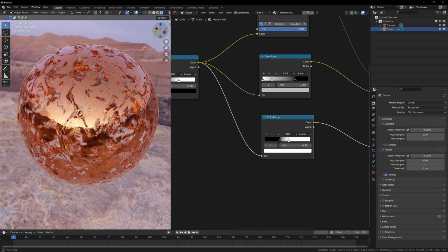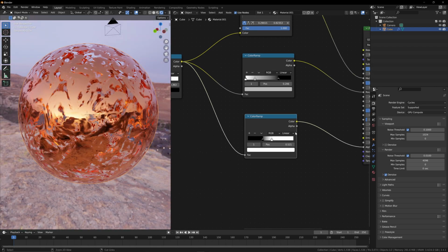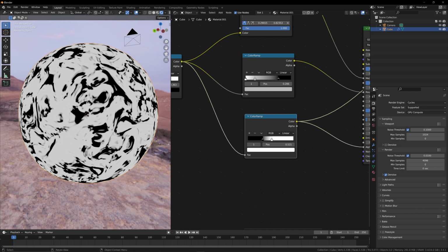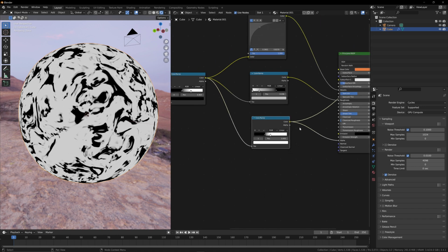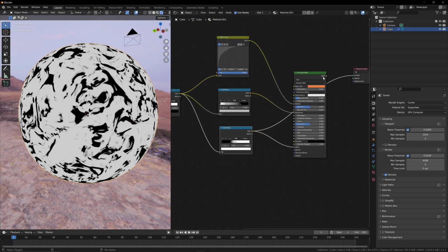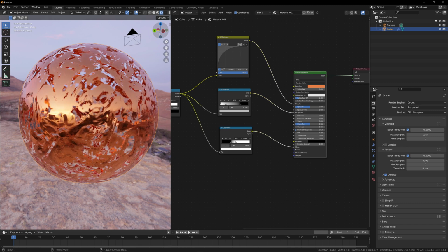You can sharpen these things up, and again, to view this, press Control, Shift, and left click, and you see what's going on here. The black is being made completely transparent, and the white is completely opaque, and any gray in between will be slightly visible. So I'm going to go back again, Control, Shift, and left click on the BSDF output, and view this